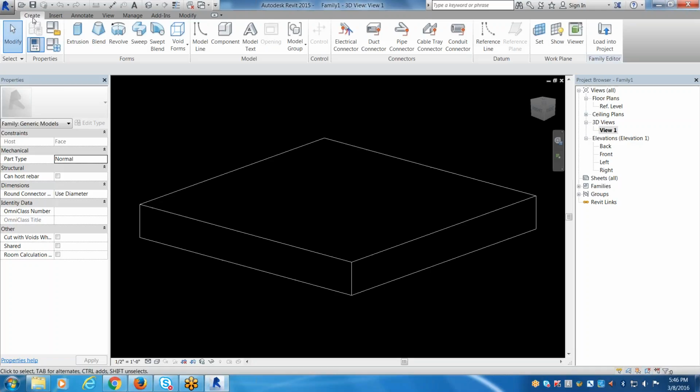And then a void is when we need to create a negative in a shape. So I would create this revolve, right? But I want this open. So if I go to void, you'll see they have the same options for these, but in void form. So I would create one that's slightly smaller in here so that I have this thickness in here. So I'd create this solid shape and then create one a little bit smaller that goes inside of here and remove all of it so that this is open, so that all I'm left with is this difference between them.